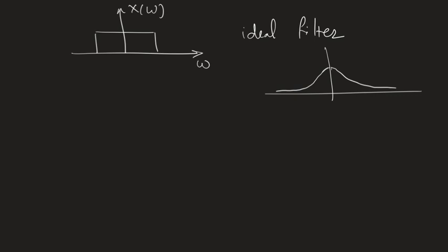Okay. And then we said that if you look at the spectrum, it never finishes. It keeps on going. If you increase the scale, it will increase with you, okay? So practically speaking, we cannot deal with an infinite number of frequencies. We'll just say that if the magnitude drops sufficiently compared to the peak value, we cut at that point and we assume that the rest is zero. So we just ignore the remaining part and we finish our signal here.